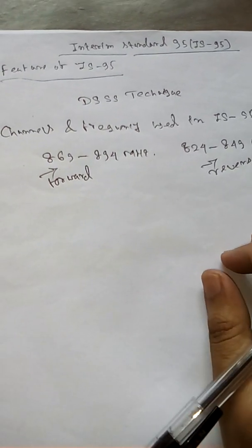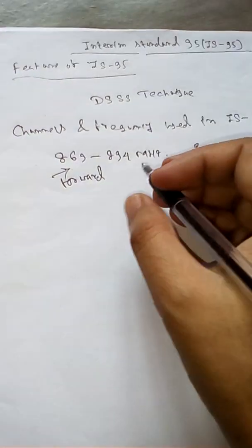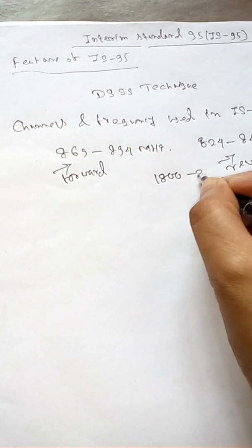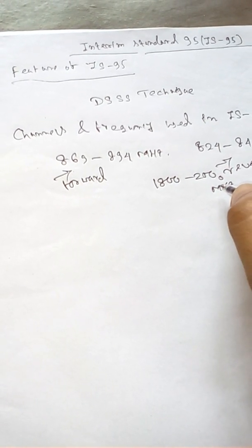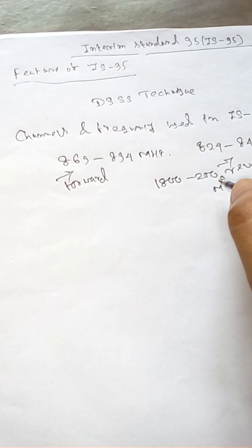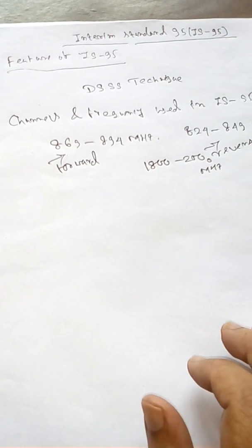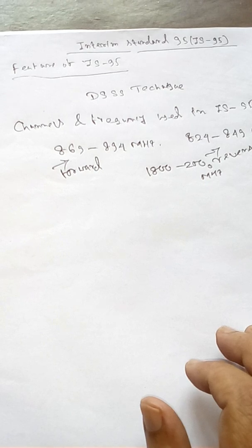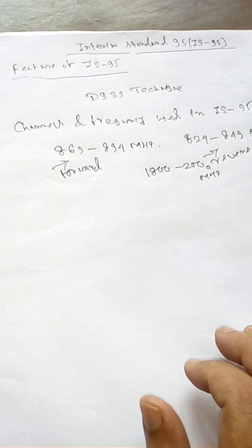A version of IS-95 is designed to use an operating frequency in the range of 1800 to 2000 megahertz. For cellular band operation, the forward and reverse channel pair in IS-95 are separated by a frequency of 45 megahertz. The total spreading factor used in IS-95 is 128, meaning a chip rate of 1.2288 mega chips per second. The spreading process is different for the forward and reverse links.